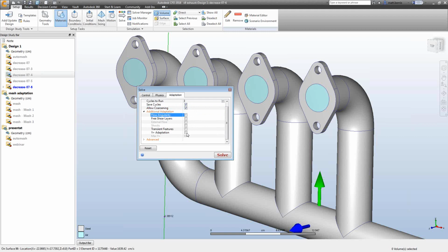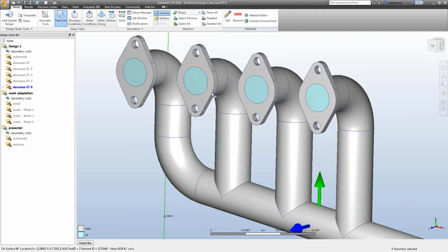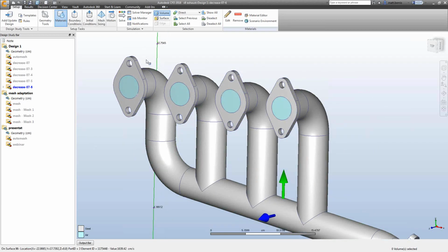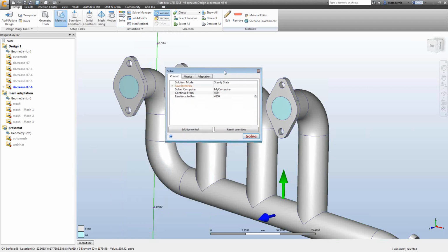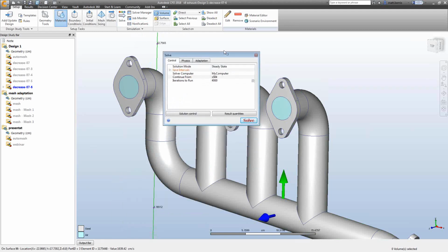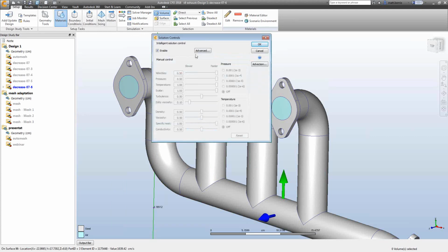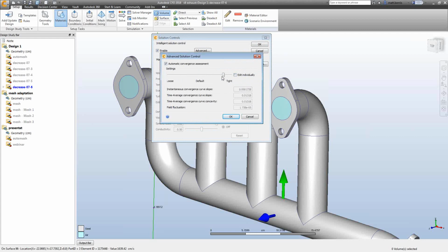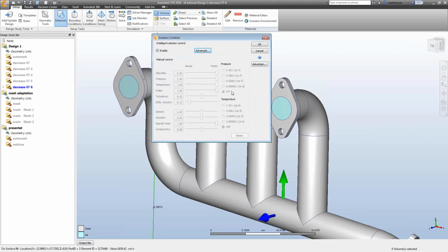So I think that's all. Just one thing I will note is that you have to decide what convergence is. Sometimes you can get stuck in a really weird situation where you can't really find an independent mesh, or a result independent mesh. Sometimes it helps to tighten the convergence criteria to tight, because these might be kicking out at different times and you're not really sure how solid it is.